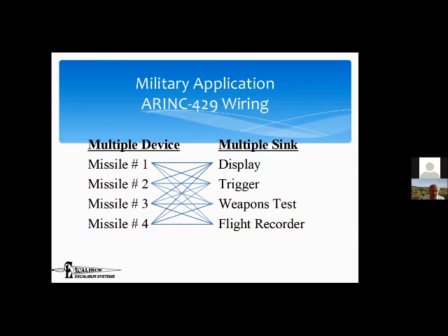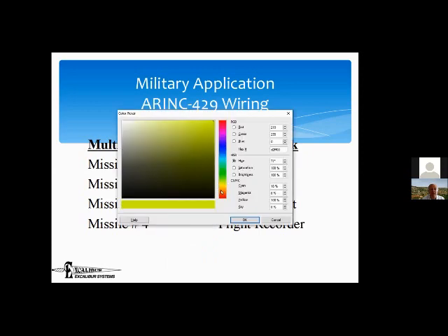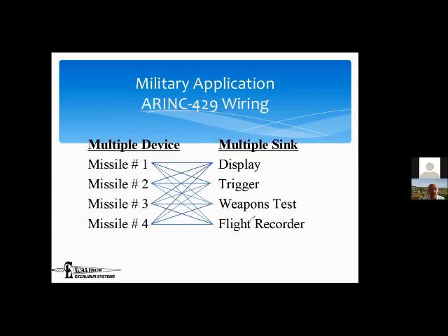The second thing is that every wire you have can potentially break. And the more wires you have, the more likely it is that one of them will break. And all the soldering points, as here, connected to missile 1, we've got 4 different wires. So let's get a pen color here, orange. Okay, so right at this point, you've got 4 solder points, and you've got the same 4 solder points for each missile. Every solder point is a weak point, and could potentially cause trouble.